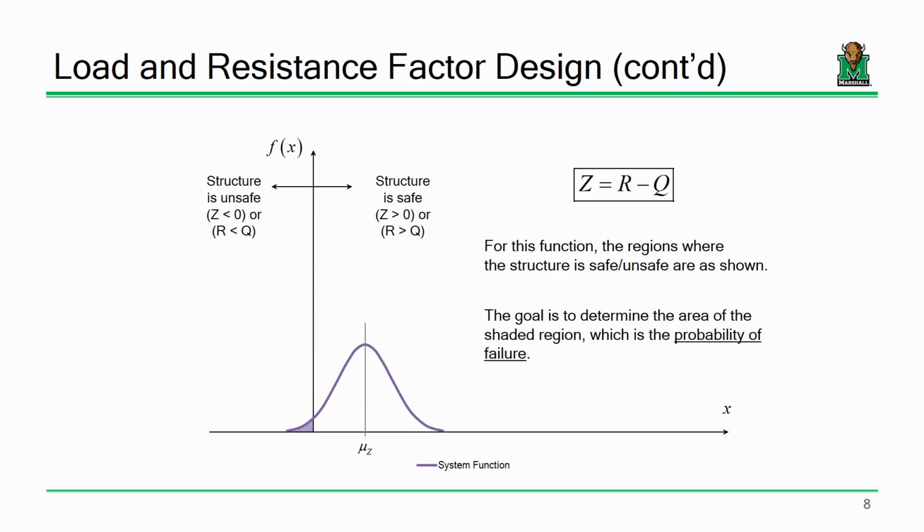You take steel design, you take concrete design, take pre-stressed, where you focus in the building side, and you've probably seen things like 1.2 times the dead or 1.6 times the live. You've probably seen that before, am I correct? Okay. If you've seen that before, when we use 1.2 times the dead and 1.6 times the live, those numbers come from trying to keep this probability of failure uniform. I mean, why is the live load number larger? Why do we use 1.6 for the live loads and 1.2 for the dead loads? Well, live loads, there's a lot more uncertainty.